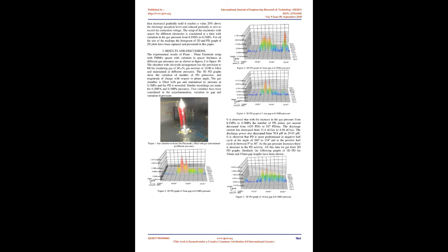Partial discharges usually produce voltage or current signals with duration less than 1 microsecond. The high voltage operating devices and the generating stations operate at very high voltages. When the high voltage is applied to an electrode gap filled with a dielectric, PD may occur that does not lead to the loss of insulating properties of the dielectric as a whole. At this time, the pulses of current are registered in the discharge circuit, the number and intensity of which can predict the probability of a breakdown of the gap.